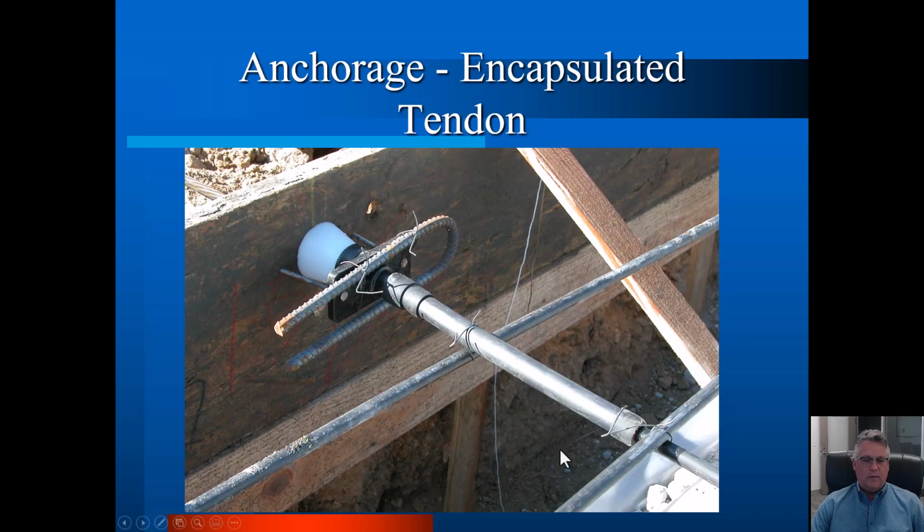So, I've thrown out the word encapsulation. It used to be, in the olden days when I was your age, that there was no requirement that the strand be kept away from all the elements. In fact, towards the dead end, the strand was often exposed. The concrete did attach to it. No harm, no foul was the thought, because it wasn't the end that's going to have most of the movement. This was the dead end that was sitting still. So it would be exposed to the concrete. But the problem is it was exposed to all the elements.